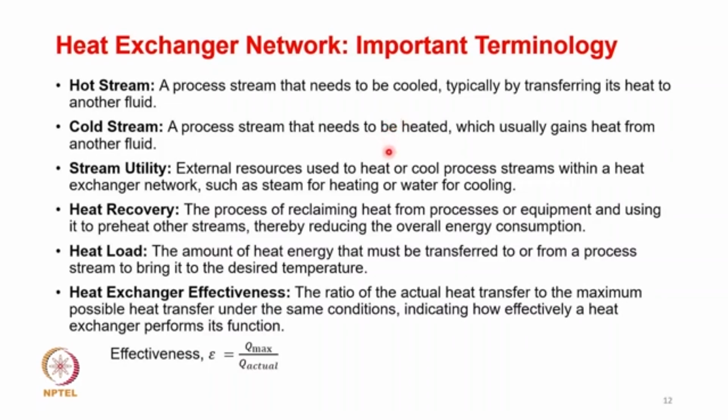Of course, a cold stream is a process stream that is to be heated, which usually gains heat from another fluid. And what is a utility stream? It is an external resource used to heat or cool process streams within a heat exchanger network, such as steam for heating and cooling water for cooling. And what is heat recovery? Heat recovery is a process of reclaiming heat from processes or equipment and using it to preheat other streams, thereby reducing the overall energy consumption.